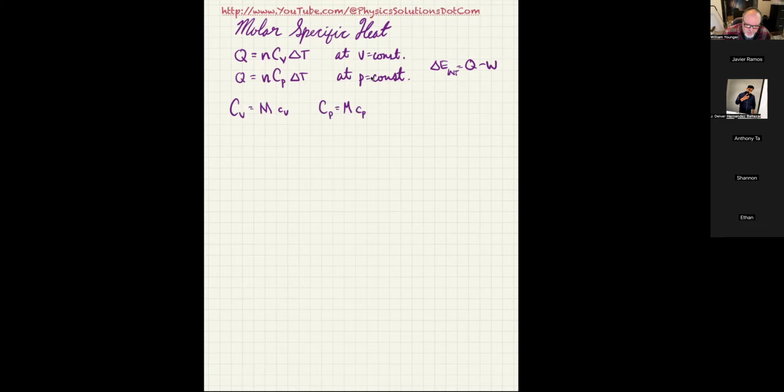So that's how you get that. Remember, the molecular weight in this case is being thought of as having units of grams per mole. So you probably need to take it into grams first off. So you're using lowercase c sub p and c sub v in grams for best results, or you have to convert it to kilograms, one of the two.